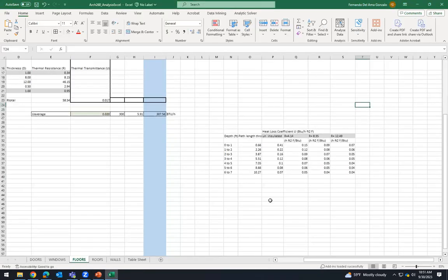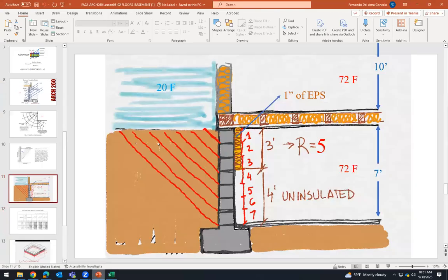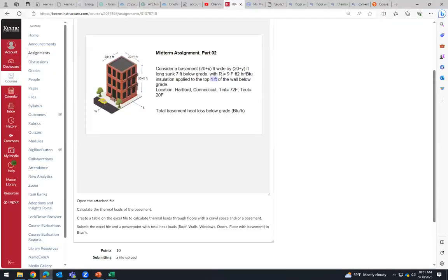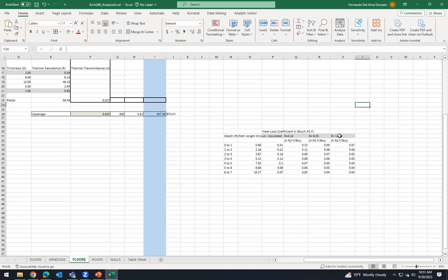Okay. And what does it mean in the table? If the R value of the wall is 9 when we have thermal insulation, then we have to select the next closest or lowest value. If we have 12 and we have 8, we have to select this column, and we have to select this column on the first foot. So I'm going to highlight this. This is the one with the thermal insulation. And then the rest of the wall is uninsulated.